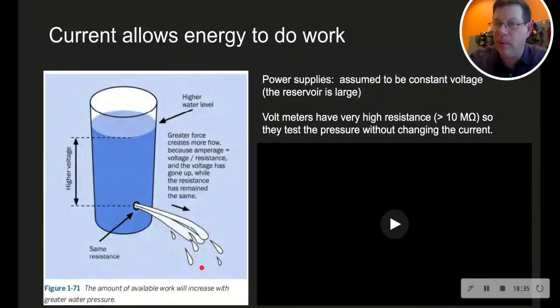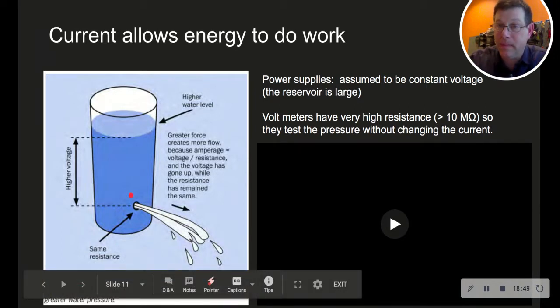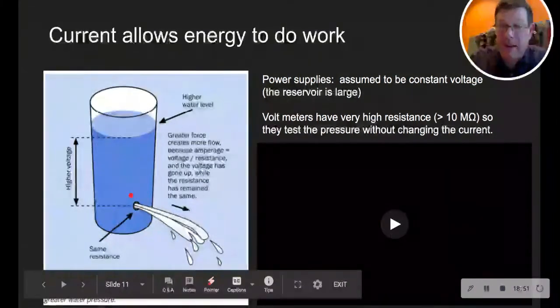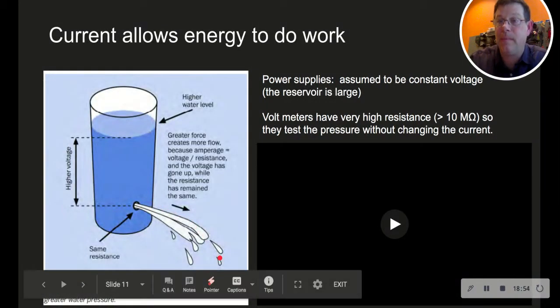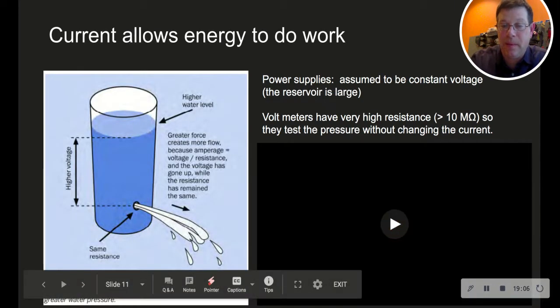What happens if you use a voltmeter for measuring current or a current meter for measuring voltage? Well, if you try to measure in a current meter across a circuit, that's like taking a functioning circuit and putting a huge hole and allowing all of the water to drain not into your circuit, but through the meter. And this is why your meter has a fuse and why you'll blow it if you actually try to keep your meter in current mode while measuring the voltage across a component in your circuit. We'll practice a bit more with these concepts as the class goes on.